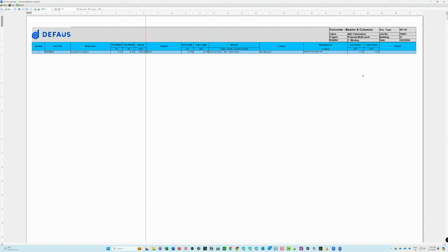The builder will still need to know how much concrete he needs to purchase for that footing. However, he may want to add a percentage of 5 or 10% additional concrete, because we know that footings are never actually dug in the ground perfectly to how we draw.